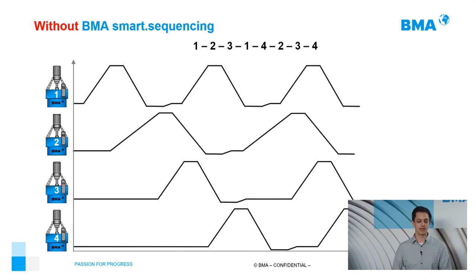And here again, we have the same problem. The first machine is ready and the second machine is also ready, and we don't want this, because now the first machine has priority, and at the end you have the first machine making 4 cycles, and the other machines are still in the second cycle. And this happened in just 10 minutes. What is happening in one campaign that takes 6 months? You have the first machine operating and having many more cycles and also much more wear than the other machines.